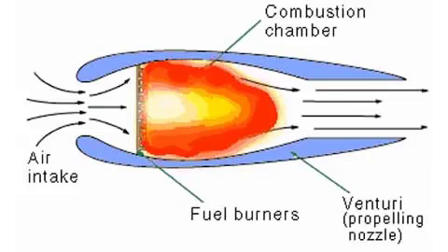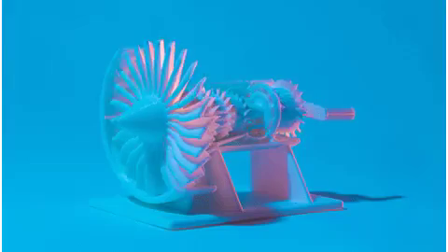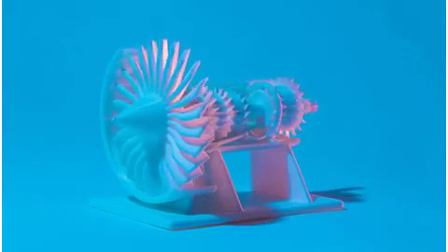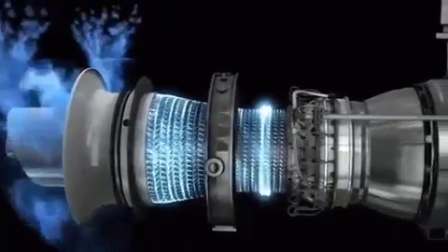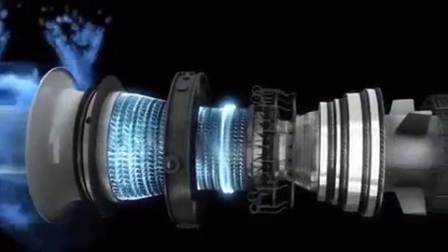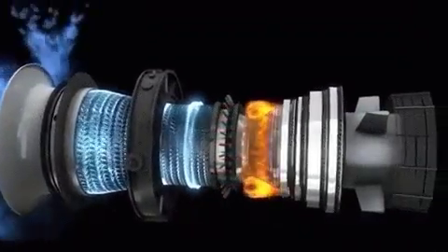Which means instead of just letting out those hot gases, they are indirectly used to suck fresh air at the same time. This is the reason we need a turbine after the combustion chamber section. After coming out of the turbine, the gases are allowed to exit the engine through a converging shaped nozzle.